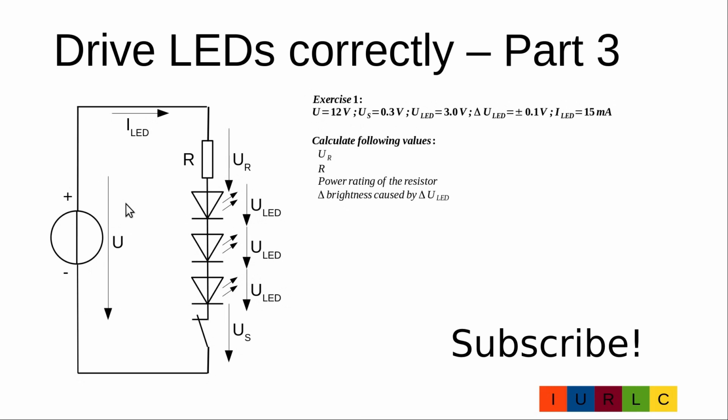Exercise 1. We have a supply voltage U of 12 volt. We have a voltage drop on the switching transistor of 0.3 volt. We have on each LED a forward voltage drop of 3 volt. And the tolerance of the forward voltage is plus minus 0.1 volt and the current through the LED should be set to 15 milliamp.